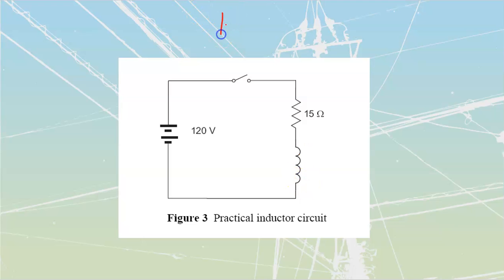Once again, we need to satisfy Kirchhoff's voltage law. The sum of all volts is going to be equal to my source voltage when I close that switch. The instant that I close this switch, the amount of current that I'm going to have is 0. At the exact instant, we're talking like instant, we will have 0 amps inside of that circuit. We've got voltage, but the electrons themselves have not started to move.